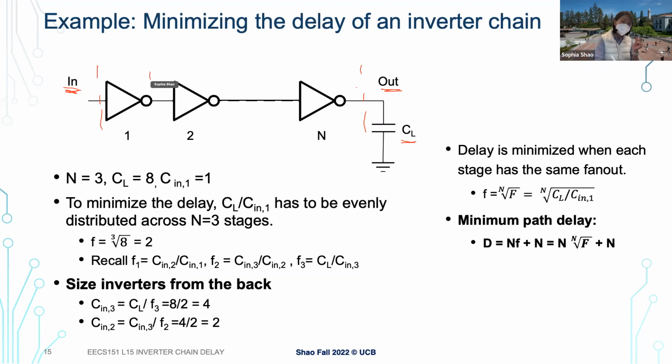Which means that, for this stage, it needs to be sized smaller than the previous stage. Here we just normalize to 1, but let's say we put another inverter before, of a particular size, whatever size it is. To balance this, this stage needs to be smaller. So far we always sized bigger, but it can also be sized smaller. The input load is too big and the output is pretty weak, so we don't need very big transistors at this point. We can do things smaller there. Good question. Everything is normalized here, and everything is relative in this discussion, right?